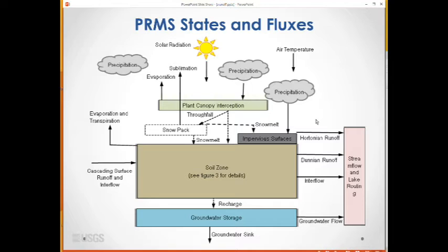Inflows to the surface runoff modules are rain throughfall as computed in the interception module, snowmelt as computed in the snow module, and potential ET as computed by the selected potential ET modules. Optional inflows to HRUs as computed in the surface runoff modules are cascading Hortonian surface runoff and capture of a specified fraction of Hortonian surface runoff in surface depressions.